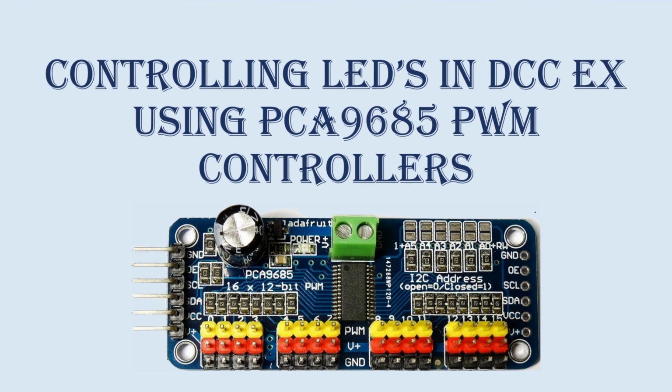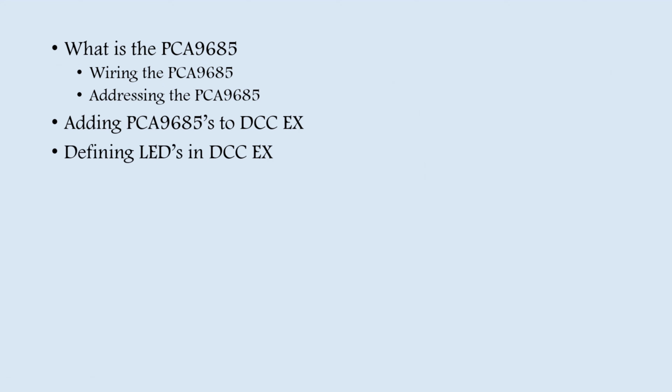Okay, let's talk about controlling LEDs in DCC-EX using the PCA9685. What we're going to do is show what the PCA9685 is, how we wire it, and how we address it. Now this is the I2C addressing. And we're going to talk about adding the PCA9685 to DCC-EX so that the command station recognizes it and knows it's there. Then we'll talk about defining LEDs in DCC-EX and what we need to do there. Then we'll show using the set and reset command to control the LEDs. This is basically the on and off.